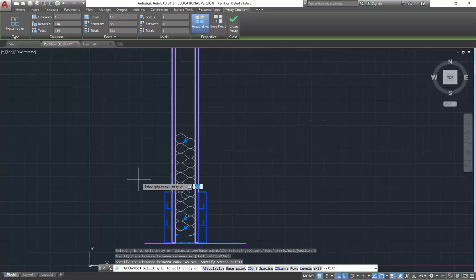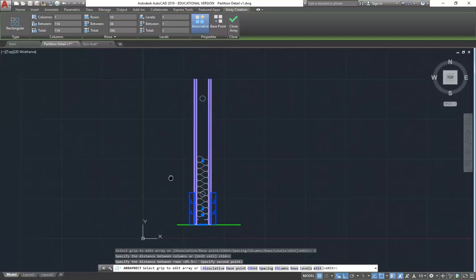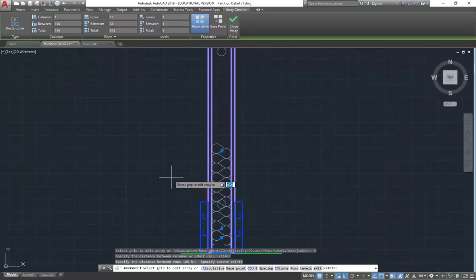Where's your array copy? Why did you do a little array and not a column? Oh, I could have done copy. I just would have had to click on each point, whereas this does all of them in one. How did you copy it? On the modify panel. So Array does the copies for you. Then how do you do it? Oh, so you've got to use the spacing option on the command line. Symbol for array.